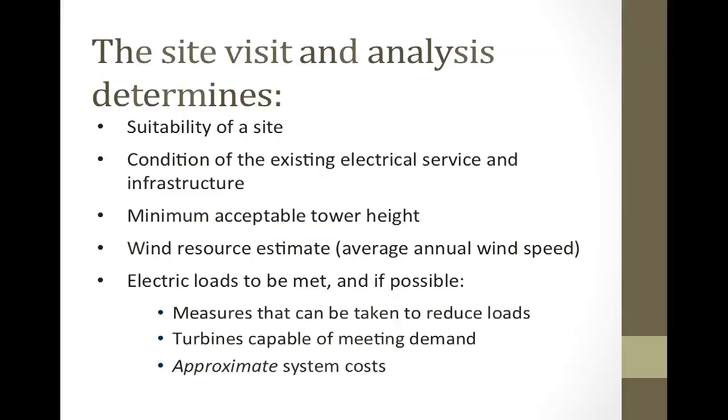We also have to look at the existing electrical service and the infrastructure. Well, how does the electricity get on the property? Is it an overhead line? Is it a buried line? What's it rated for? Can it handle the amount of power that we'll be trying to put on this? Perhaps it's old, maybe it's fuses. So in some cases we're going to be looking at them and we'll be making recommendations that an electrical service be upgraded.